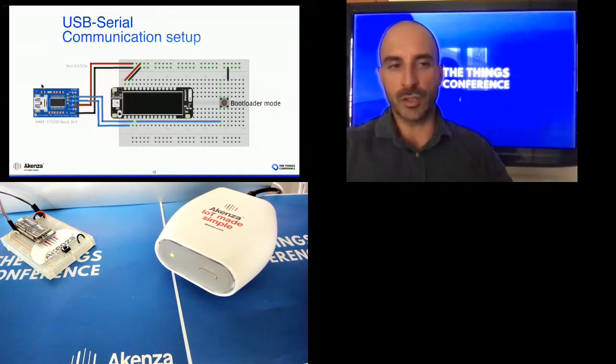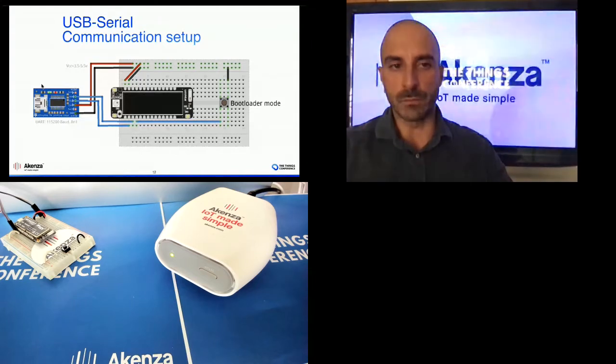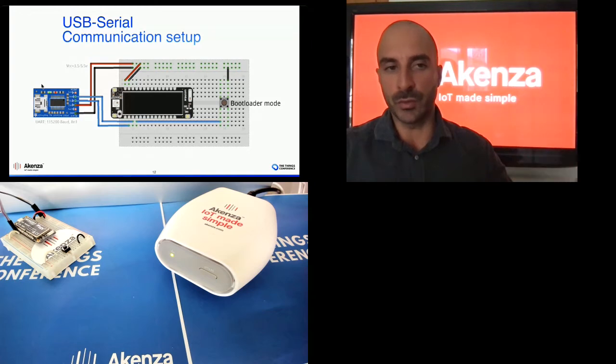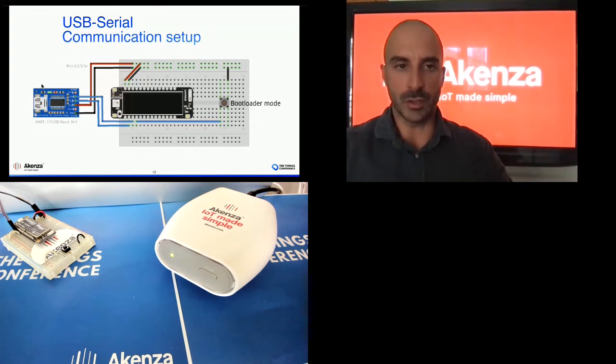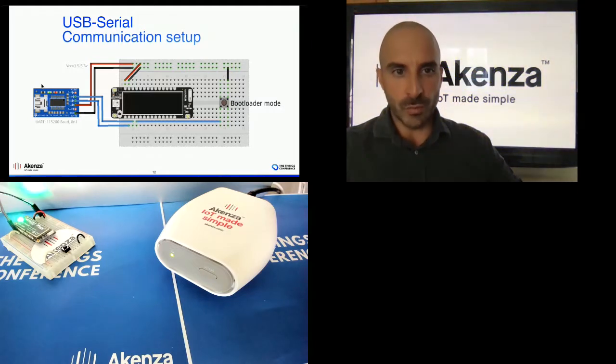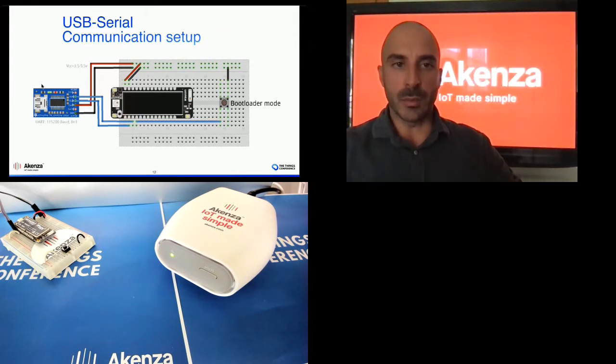We did just adjust the ratio, the speed to transmit the baud rate. Sorry, the baud rate that we used to transmit the firmware on the chipset. So for the development, we have used PlatformIO. This is an open source project, and starting from now, I just invite you to try it by yourself. We have just taken the project from GitHub.